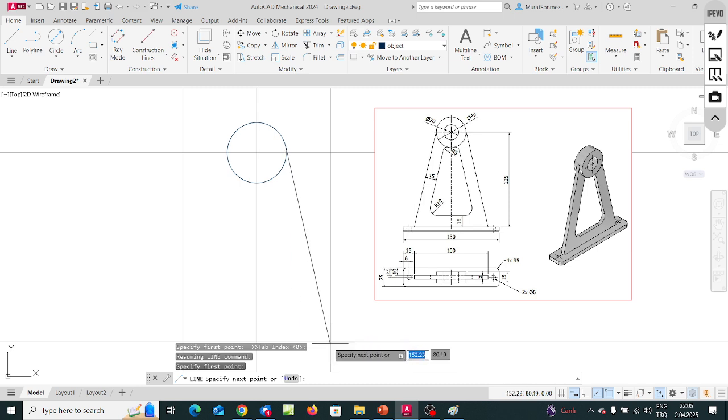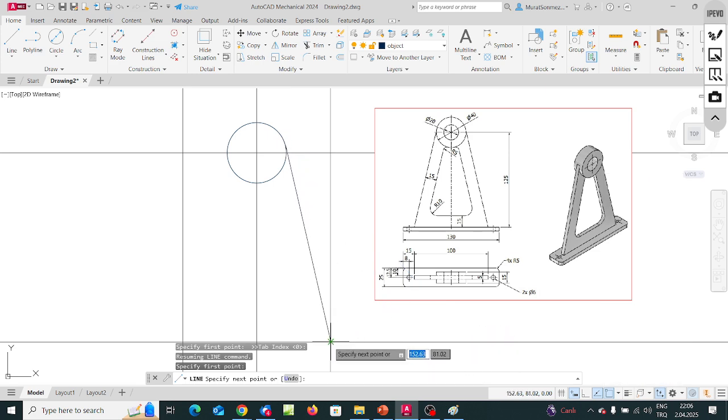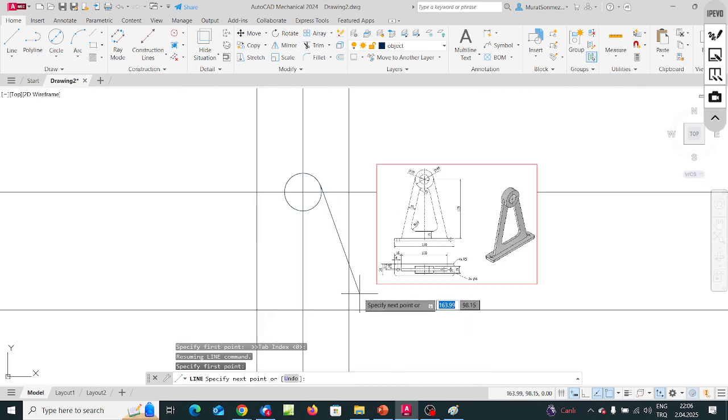But since at present there is no snapping enabled for intersections, drop this list and enable the intersections by selecting the intersection option for snapping. While this intersection can snap the cursor, it can be indicated. The green cross is the symbol used by AutoCAD for such a highlighting.